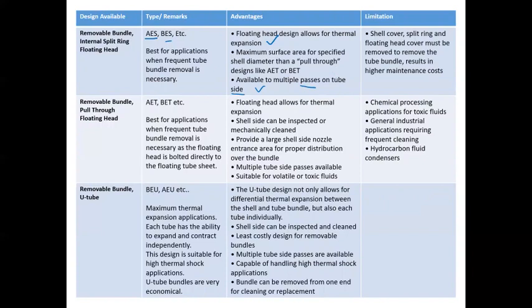But the limitation is that the shell cover, split ring, and floating head cover must be removed to remove the tube bundle. So we cannot easily remove the tube bundle only, but we should remove the shell cover and split ring. So the design is a bit complicated, and we can have a higher maintenance cost.